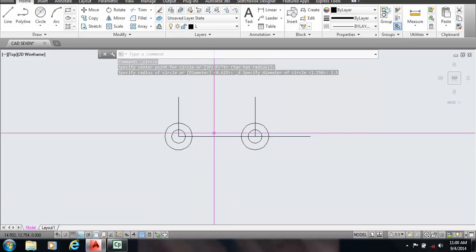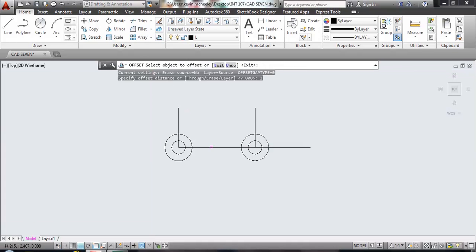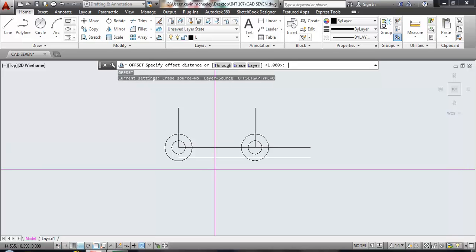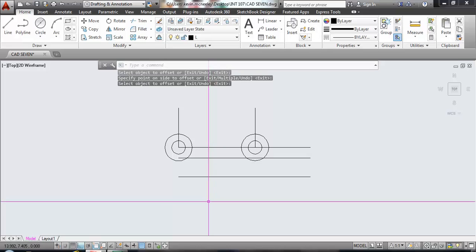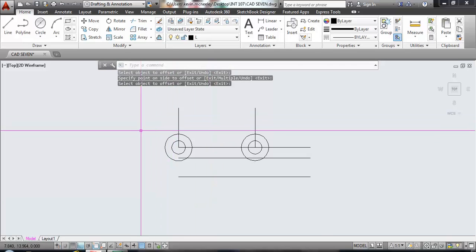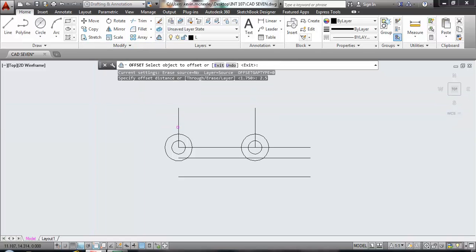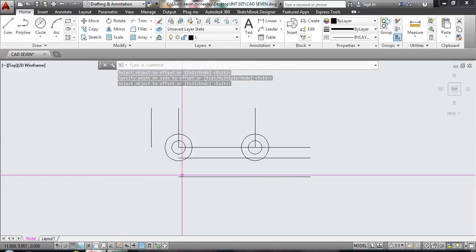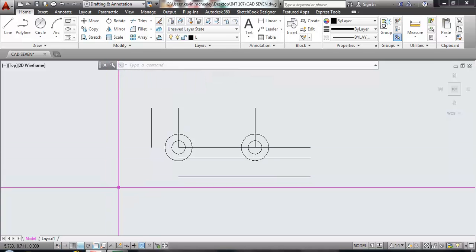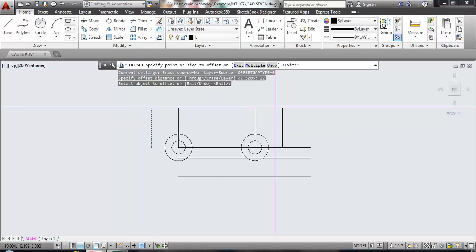And it looks like from the center down there's an inch, so I can offset 1 inch. Then I can offset down from that 1.75. Alright. From the center out is 2 1/2. Offset 2.5. And I can connect that corner. And then the total length is 12, so I can offset 12. Bring that over here.